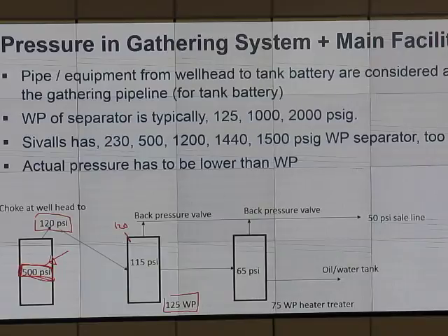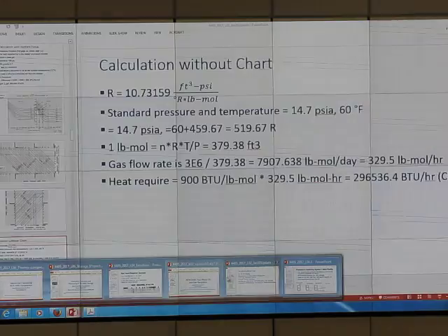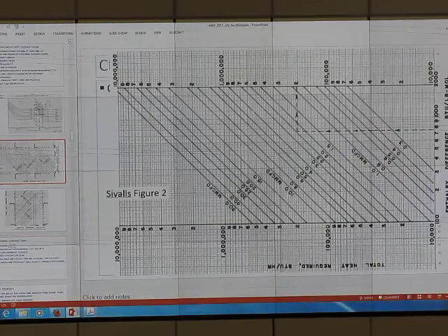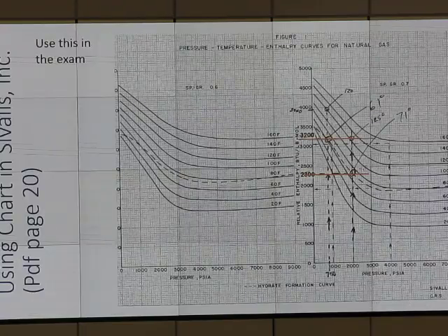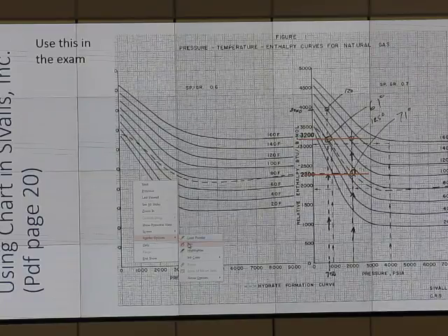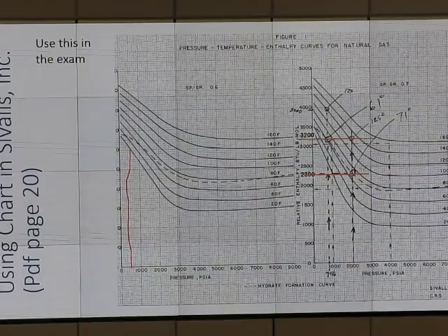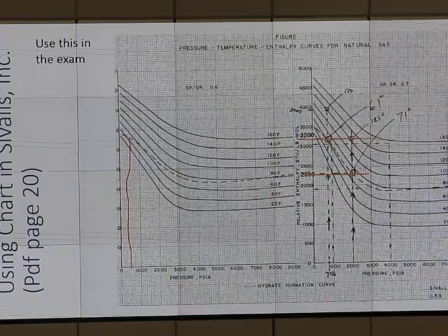If you have some gas, do we worry about hydrate? Probably not. Why is that? Look at this hydrate chart. This chart can give you some idea about where you have hydrate. If you have 500, it should be very, very hot, so you don't really form hydrate.